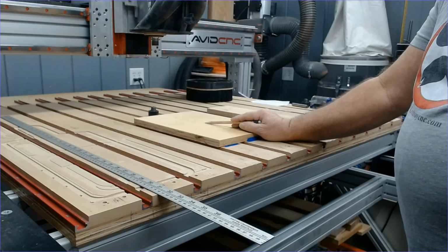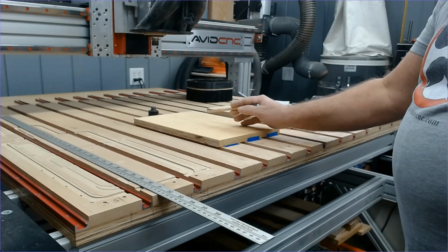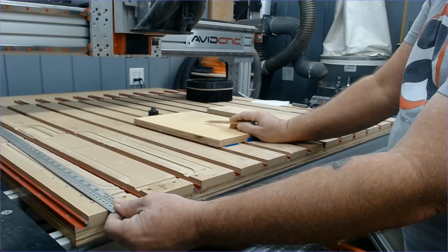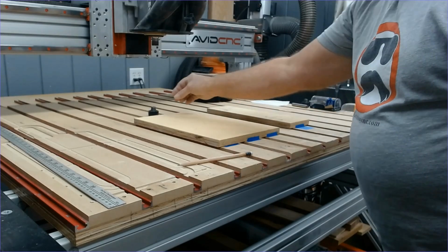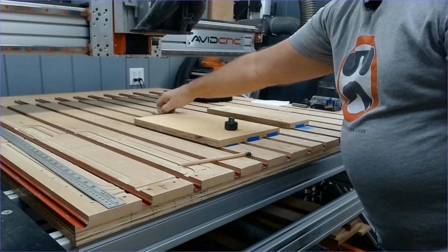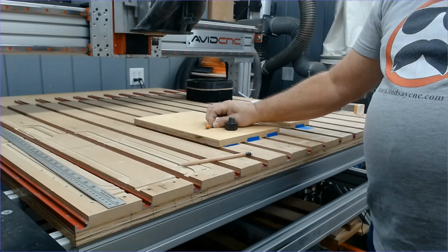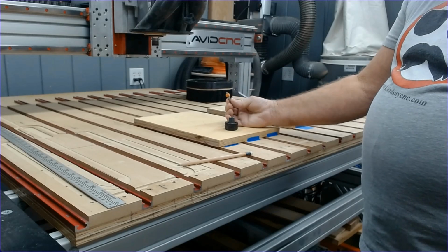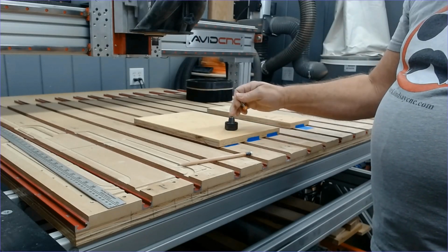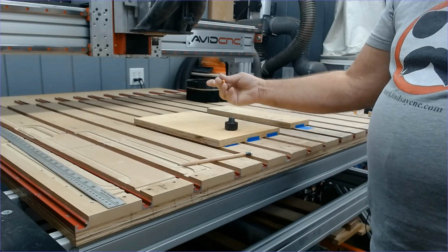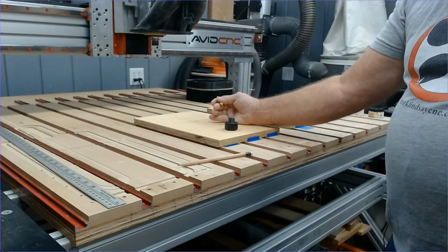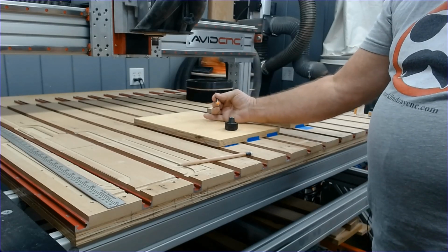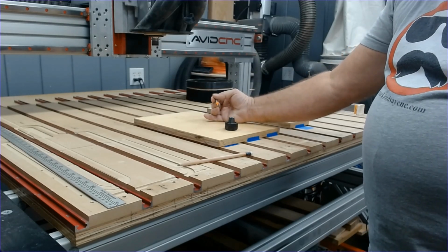So now how do I set my CNC router to XY0 right here? Well, that's best accomplished with a bit that has a sharp point to it. So I have a 90-degree V-bit here, and this is what I'm going to use to set my XY0. I'm going to go ahead and put it in the collet and put it in the spindle, just hand tight. It doesn't have to be wrench tight to set XY0, because that's not the bit that I am going to use in the first tool path.